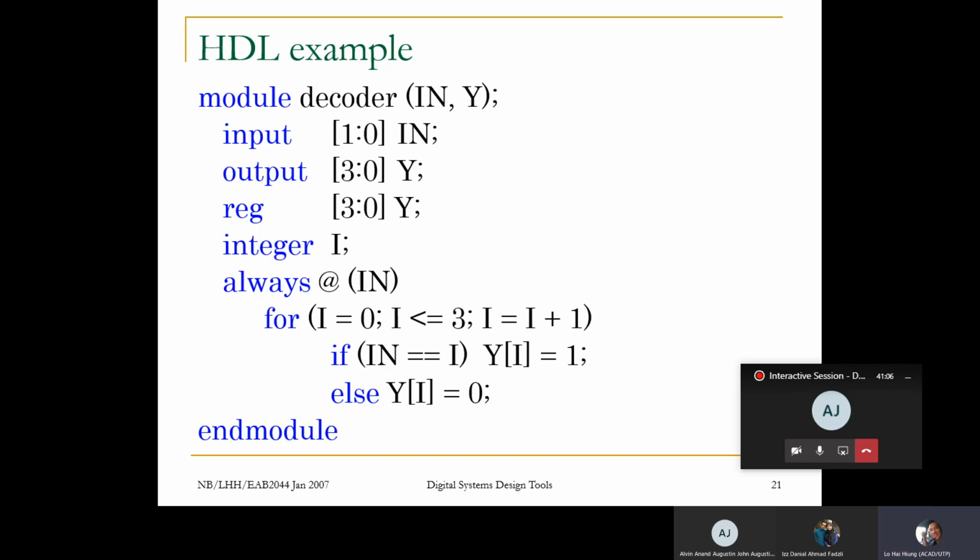Here are some examples showing a bad way of using integers. Here you're using 32 bits for what? A 2-bit operation. This is a 2-bit operation, but you're using a 32-bit value. So this is the main reason why we don't use it in hardware design.